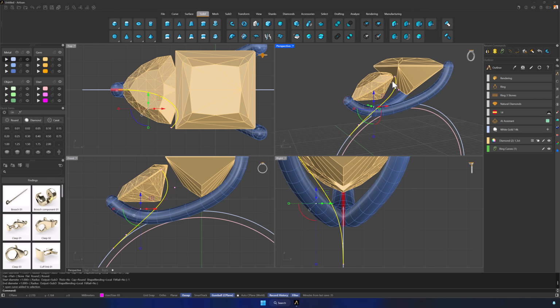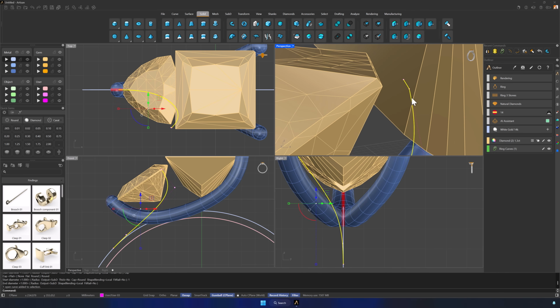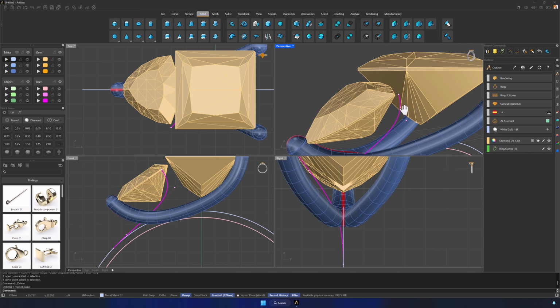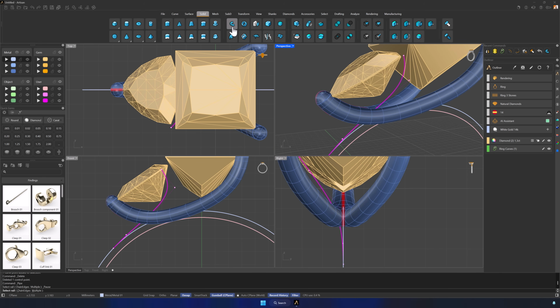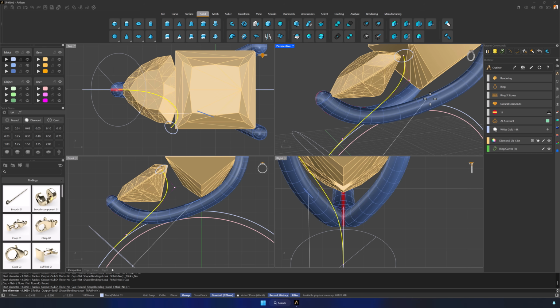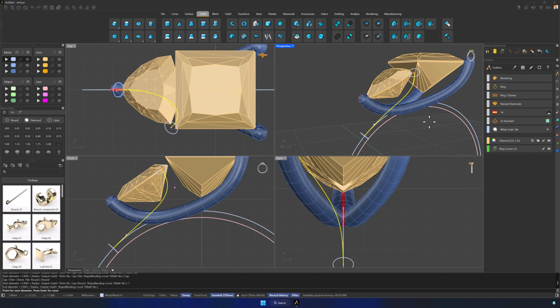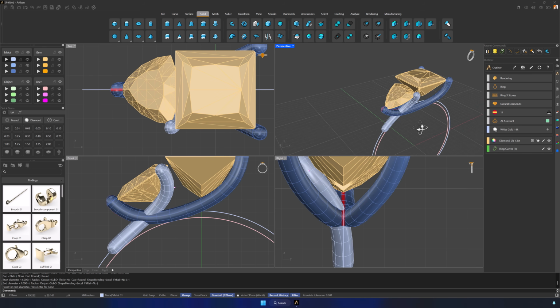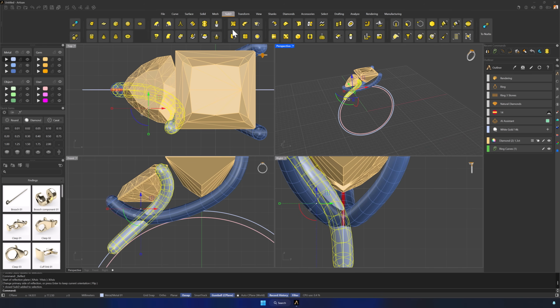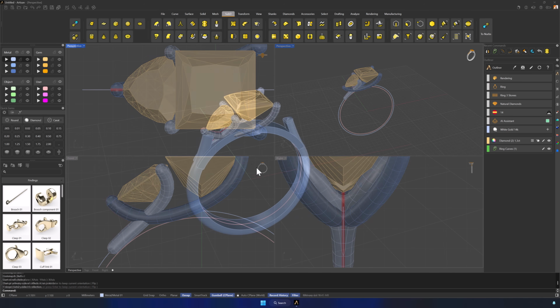First, delete the junction point between the edge and the blended curve. Then select it again and run the pipe command. Same as before, with diameter mode active, output set to sub-D, cap set to round, and a diameter of 1 millimeter. Now go to the sub-D tab and use the reflect command. Select the x-axis, and now we have our second setting completed.